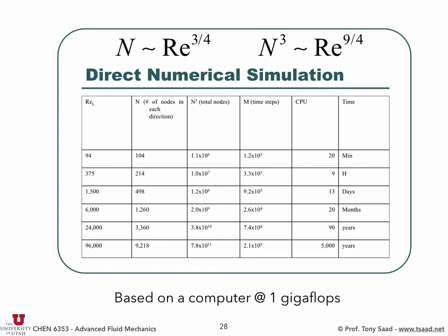The way you do it, you want to repeat the simulation and change the inlet conditions, perturb the inlet conditions a little bit, and then get another solution, another solution, another solution, and then you get statistical properties to understand what turbulence is doing. Otherwise, with one realization, you cannot understand turbulence, okay? So that's a problem, okay? We cannot do DNS except for very small Reynolds numbers. There are people who do it, for certain cases, certain types of problems, but it still takes a few months, and that's very expensive. Okay, and there are also issues with parallelizability of these, so that's a different world in computing.